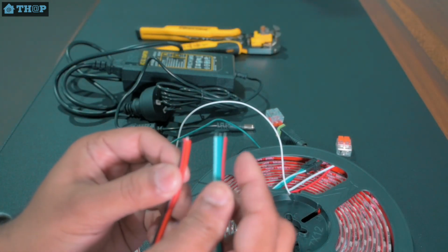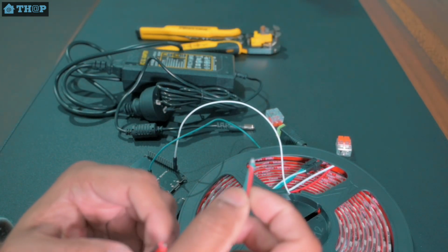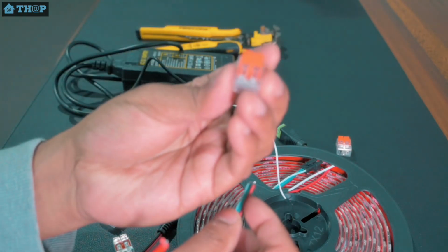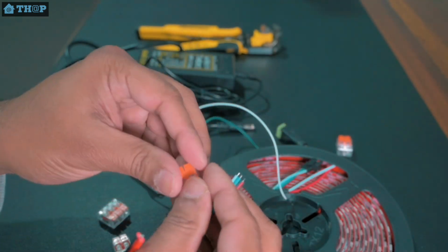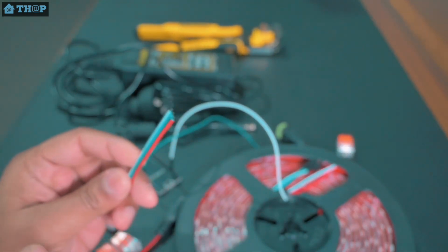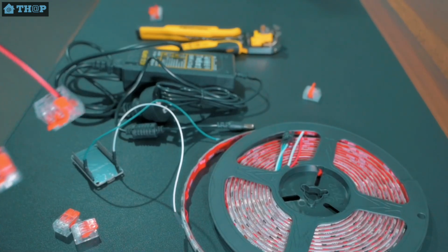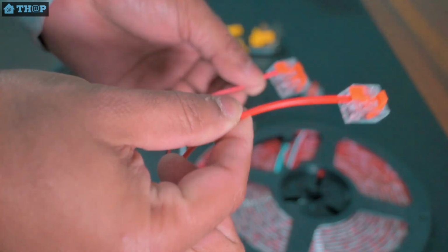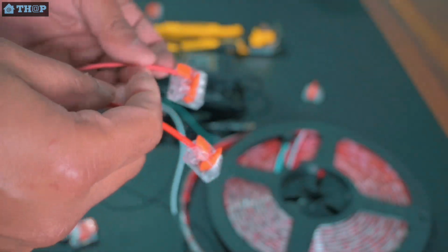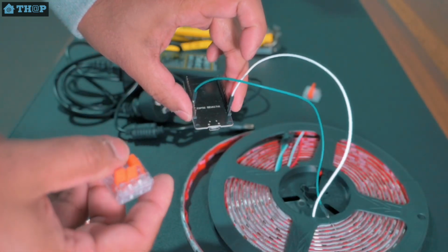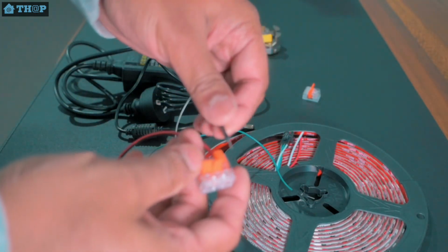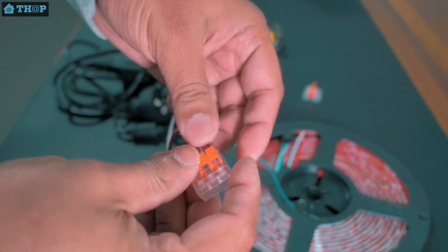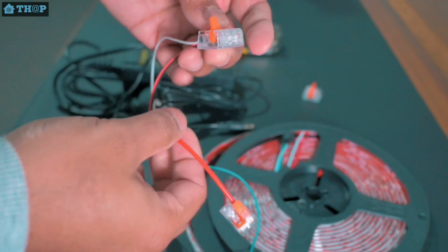Yeah, and then finally I'll connect the greens together, and green will function as a data input. I'll use the solderless connector for connecting the greens together, and the green is the one which gives instructions to the LED. Right, now I have these two power inputs, the ground and the red is the power and black is the ground. So we need to connect these to the respective ones, so the ground to the ground, which is the white from the ESP32 board. So let's connect the grounds together like so, and let's make sure the connection is tight.